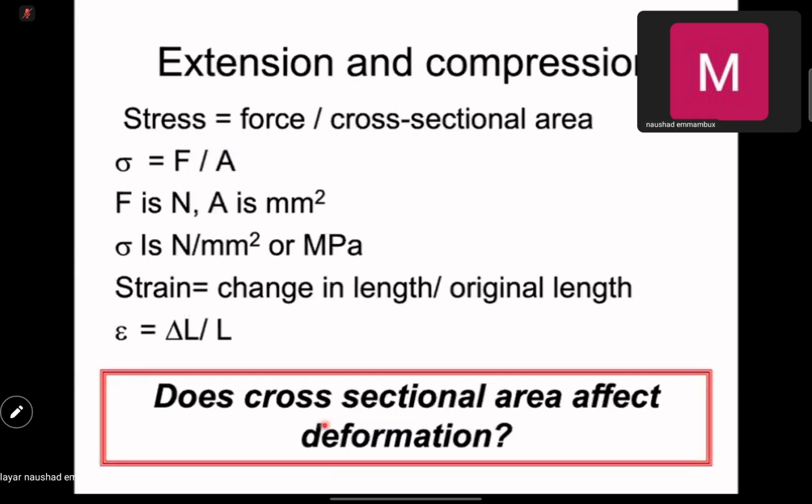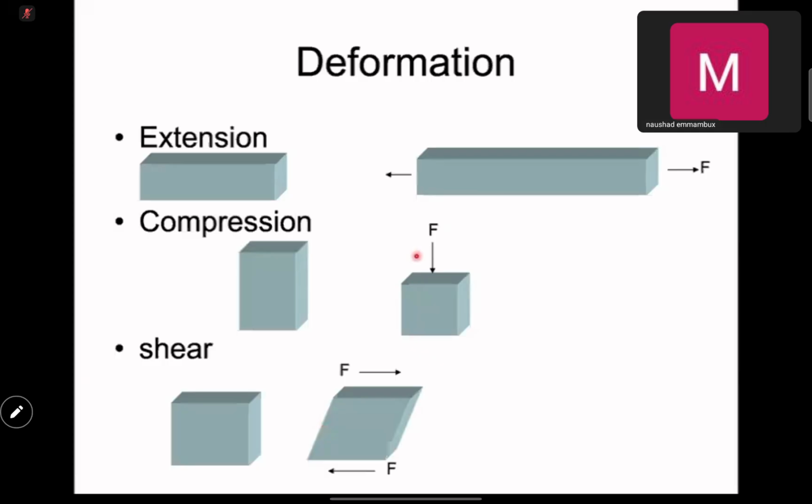Okay, so the problem is that people always make some types of errors when they do deformation. You can use, for example, a texture analyzer to do the first two. The third one, you really need a rheometer, especially for angle of deformation. The main problem people have with a texture analyzer is that it's very difficult to interpret the results if we don't know what probe you've been using.